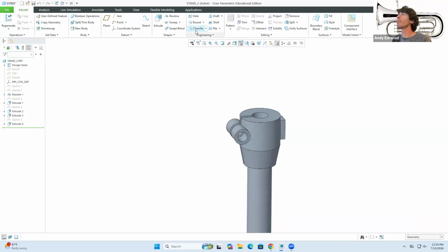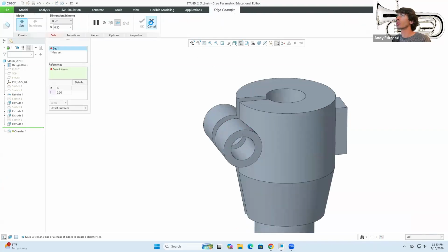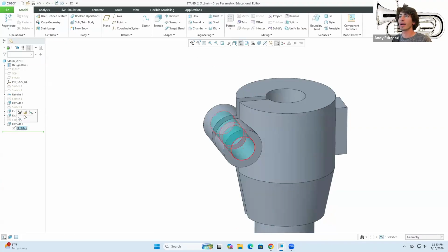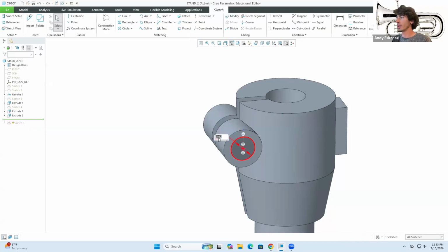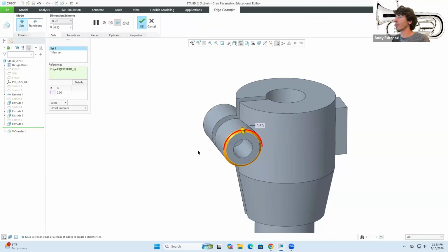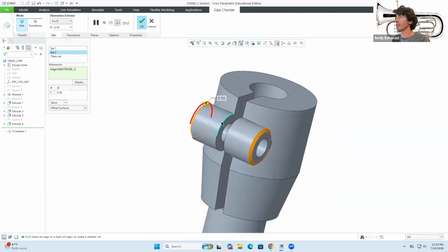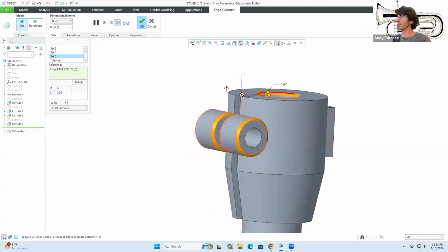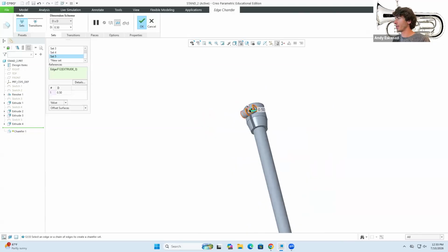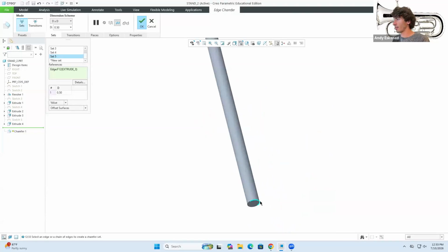So I'll go here, go to chamfer. Let me go back there to edit that to make that a 4. Click on OK. And now let me chamfer 0.5, 0.5, 0.5, 0.5. Essentially all of the interior is 0.5. Not there, and why not there too? I'll click on OK.